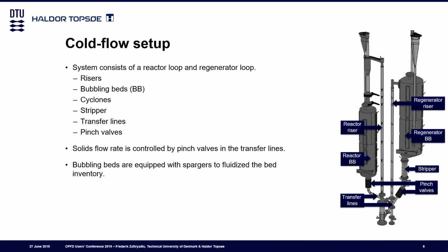So we have a circulating flow of solids, and then we have pinch valves, basically small orifices that can be enlarged and shrunk to control the solids flow rate through the system.